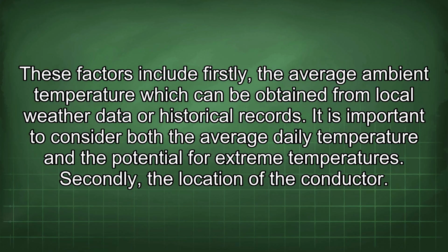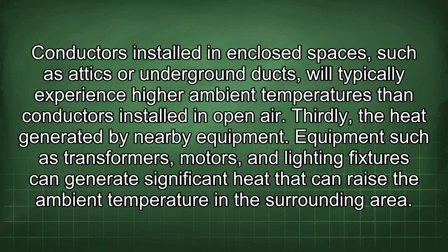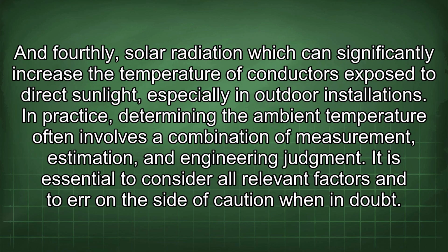Secondly, the location of the conductor. Conductors installed in enclosed spaces, such as attics or underground ducts, will typically experience higher ambient temperatures than conductors installed in open air. Thirdly, the heat generated by nearby equipment. Equipment such as transformers, motors, and lighting fixtures can generate significant heat that can raise the ambient temperature in the surrounding area. And fourthly, solar radiation, which can significantly increase the temperature of conductors exposed to direct sunlight, especially in